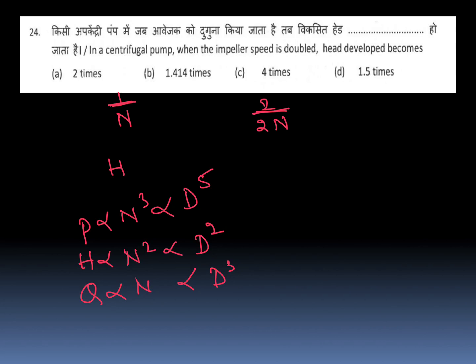Here in this question, when impeller speed is doubled, what is the head developed? So head and speed, this relation you have to consider.